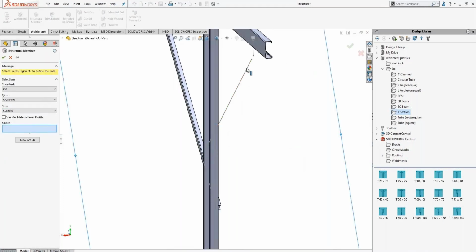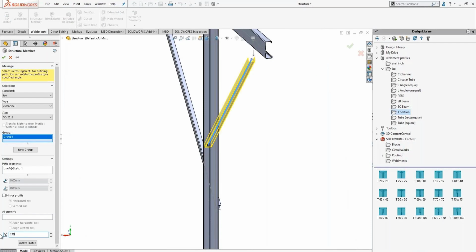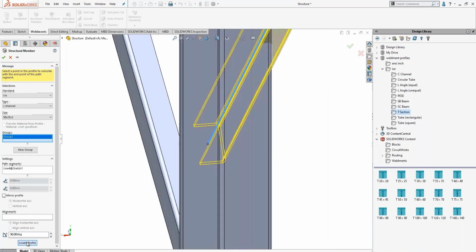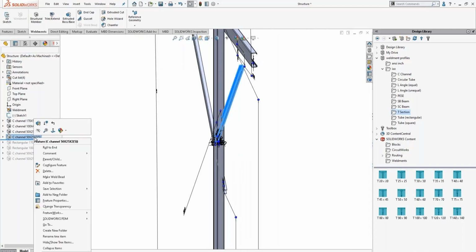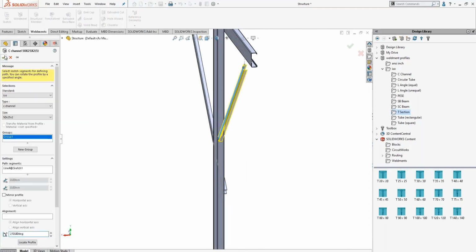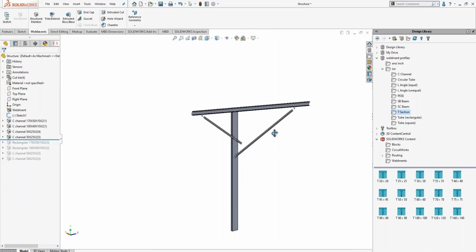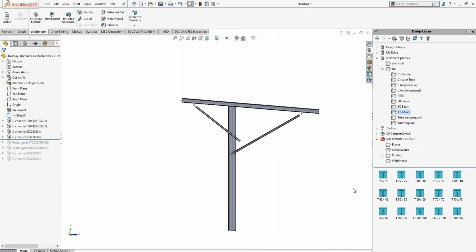So as you can see, I'm just selecting from a single sketch. I'm taking multiple weldment profiles in a single sketch, and SolidWorks is so flexible that it allows you to easily manipulate your designs in such a way that they don't take much time in creating those fabrication units, and yet you can also create your custom weldments and customize them inside your weldment profile, making sure that you can extract the cut list, which will be helpful for fabrication, helping your fabricators to do an easier job.